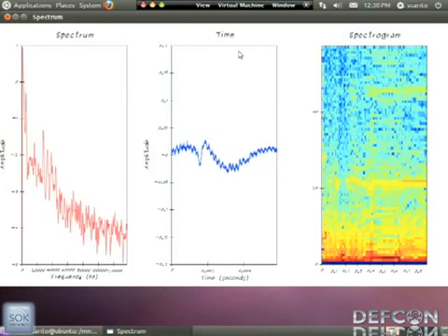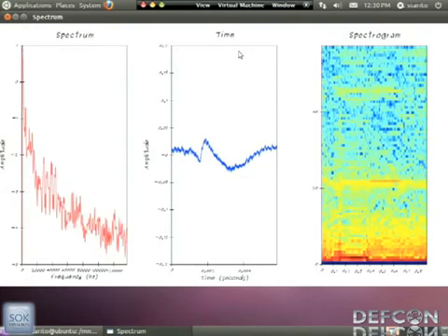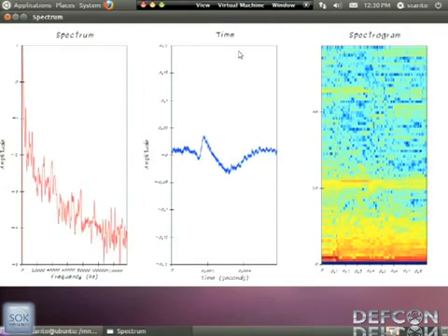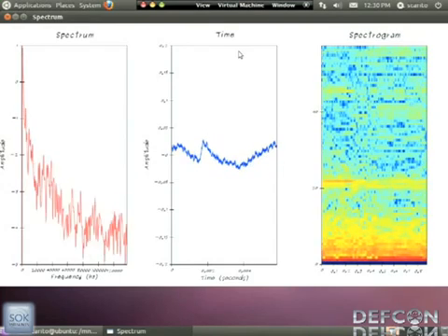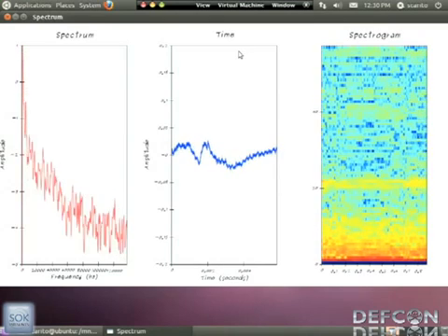And the other thing, which I haven't actually seen yet, which I'm a little surprised by, is this thing operates in the Wi-Fi band. And there's a lot of noise. I'm not exactly sure why that's happening. That wasn't happening before. But what you do see occasionally is these pulses kind of towards the top end of that. And that's actually Wi-Fi signal bursts from the thing transmitting.